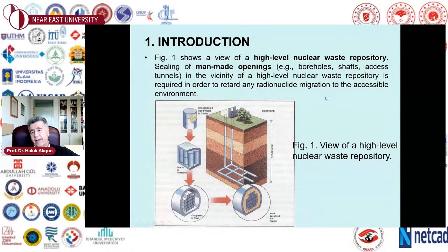In the first objective, I will talk about bentonite sand mixtures, selection of an optimum mixture, determination of some geotechnical properties, and also some borehole stability analysis. After the mixture is selected, we have to do some stability analysis in terms of determining the shear stresses at the interface, because these axial loads produce shear stresses at the interface between the sealant and the host rock.